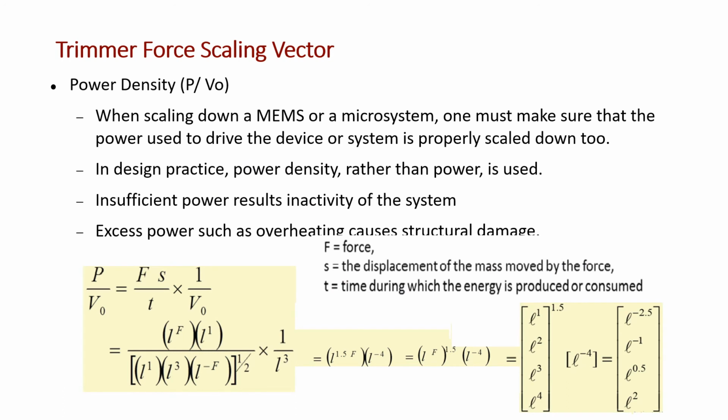When we are scaling down or miniaturizing a MEMS or a microsystem, we have to ensure that the power used to drive the device or system is properly scaled down too. And in practice, we use the term power density rather than power. Power density is defined as the power by volume. The power density is an important factor because insufficient power results in inactivity of the system, whereas excess power results in overheating and structural damage of the device.